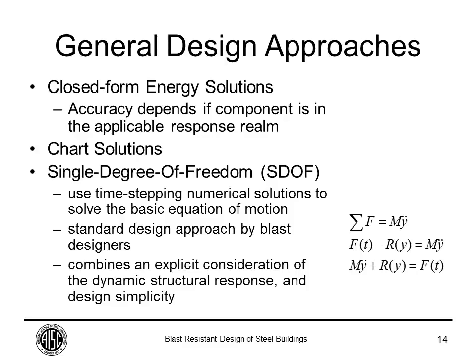The downside of the closed-form energy solutions is that your component needs to be clearly in the right and applicable response realm. In other words, it needs to be clearly controlled by the impulse of the blast load, or it needs to be clearly controlled by the pressure of the blast load. We're going to see an example of a closed-form energy solution, and we're going to discuss it in a little more detail later in the presentation.